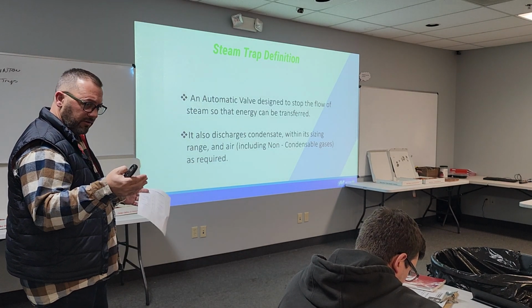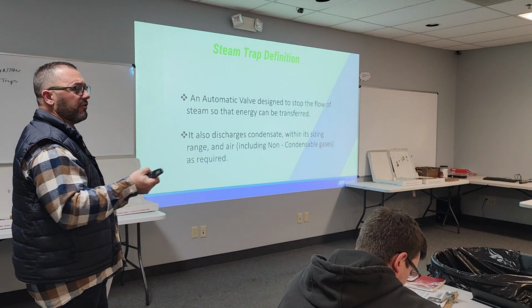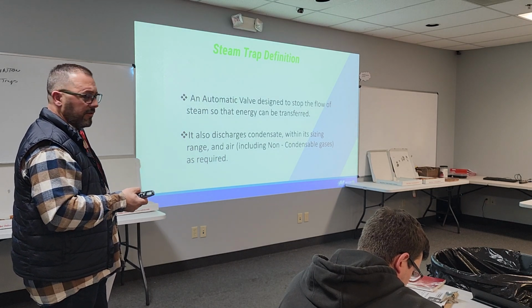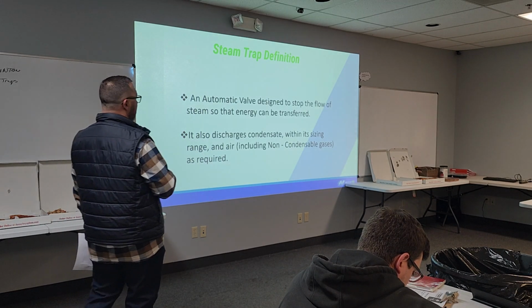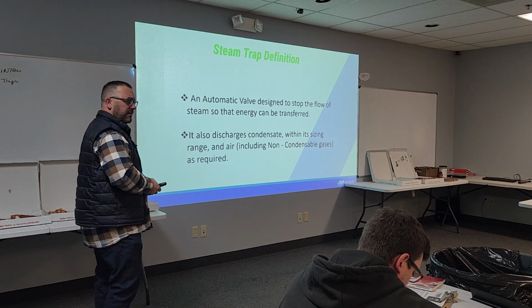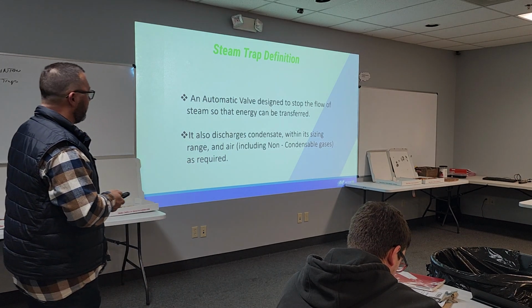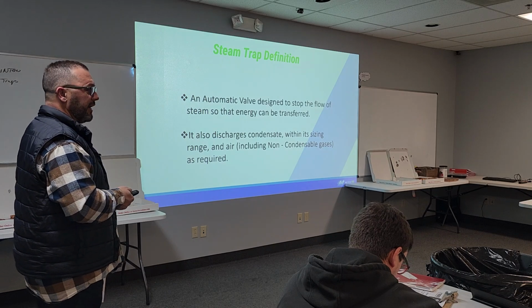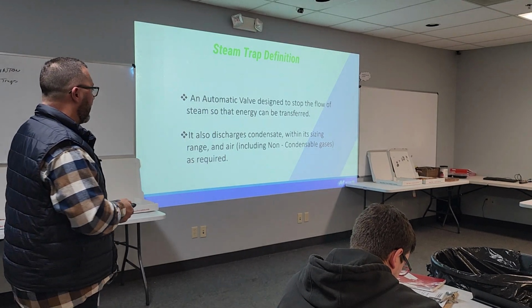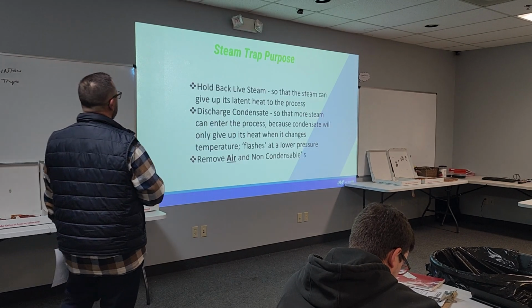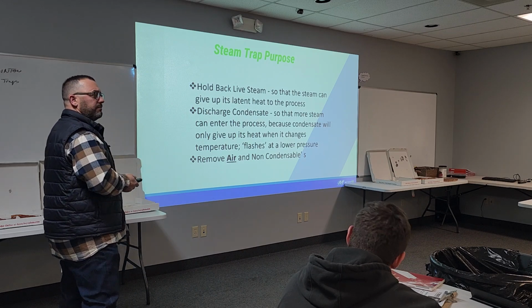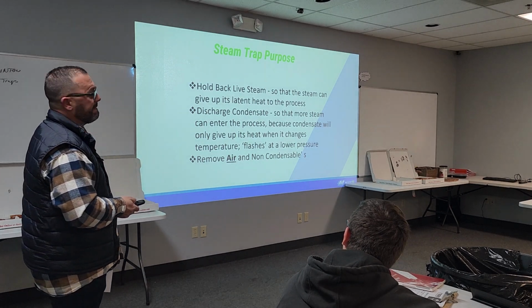It's going to take a lot longer to get started up, and you're going to have to crack strainers, the valves on strainers or something, to get that air and the non-condensable gases out. Air is, you guys likely know it a lot better than I do, a massive insulator. Massive insulator. We're trying to heat stuff up, not insulate it from the heat.